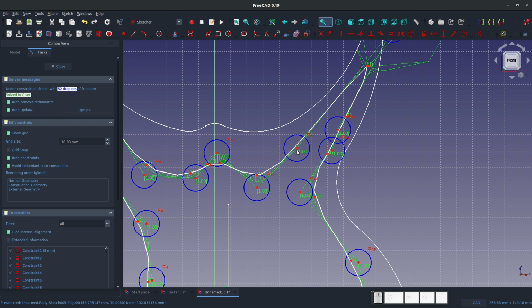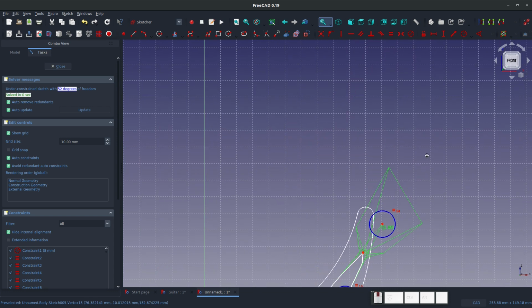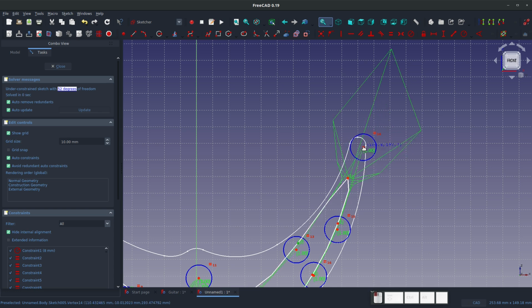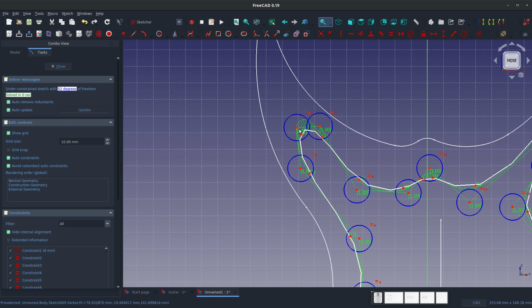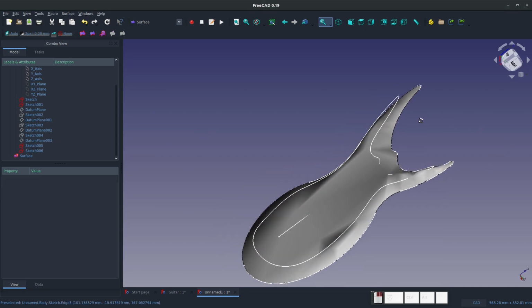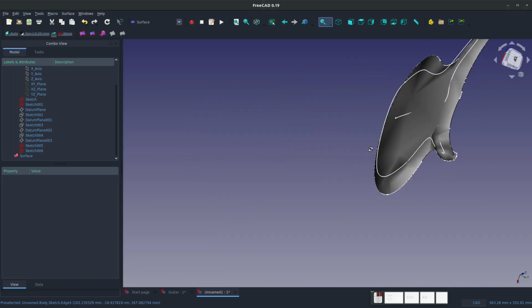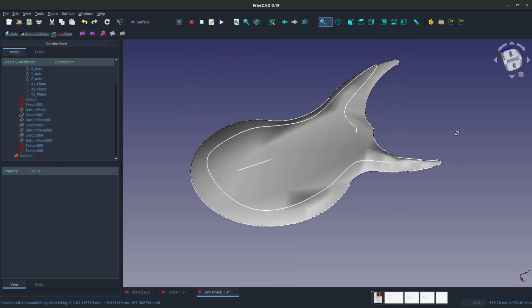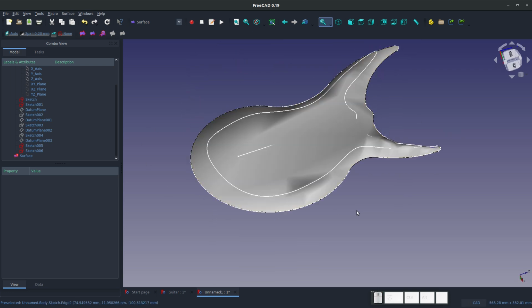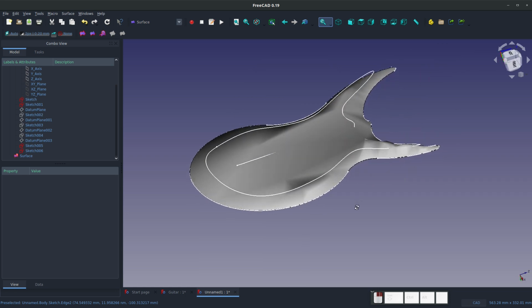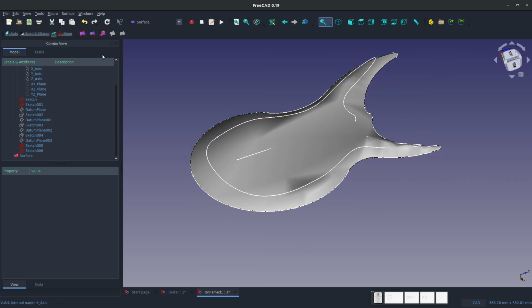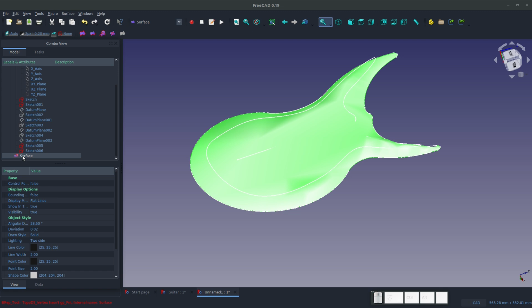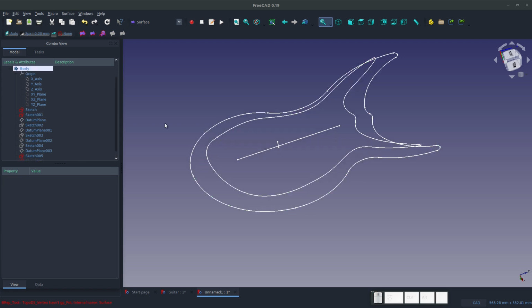And that's one thing. It really helps to add a lot of points on your B-splines for something like this, because you can help to fine-tune exactly how you want it to go. Look at that. That's cool. We'll close that. And yeah, I think we have parametrically updated. So I think that's actually a better surface. I'll leave that. Now, next step of our guitar, and it looks like I created a little error there, so I'm going to try that one more time.